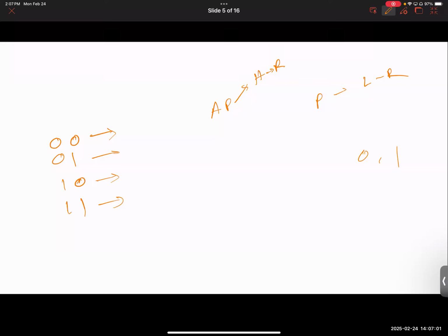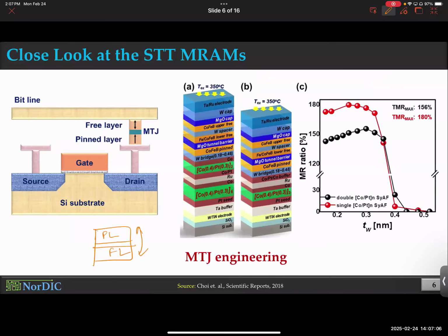So people have been trying to, I will discuss this in greater detail towards the end of this course, but just to give you a sneak peek, people are trying to have MTJs with multiple free layers, so that you switch one, you get intermediate resistance. You switch 2 together, you get slightly higher resistance. You switch 3, and so on, right? The more layers you switch, the more resistance levels you get. And it's very difficult to control, obviously, but it is being proposed, it is being studied.